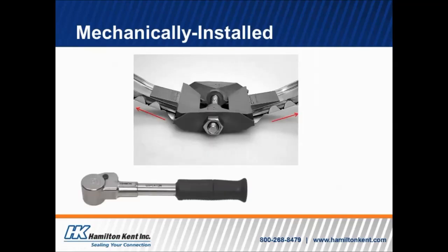So this is a mechanically installed boot that has a ratchet style of tightening mechanism. There are a variety of different styles out there that different producers of boots have, but this is one that we have, and it's fairly popular. It just takes a ratchet to tighten that nut on the outside. What that does is create force that goes out to the right and to the left where those red arrows are on the hoop, and then tightens it up against the inside of that concrete hole.